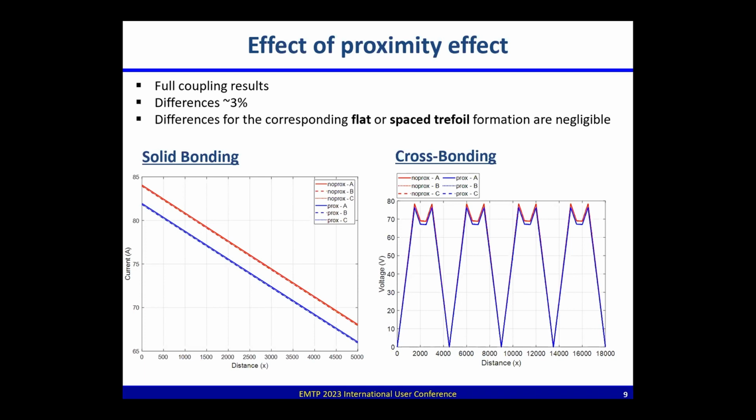Of course, because this is a trefoil case, the differences are observable. Let's say they're not that high, but they might be of interest from a technical perspective. But if we move to a flat arrangement or to a spaced trefoil formation, of course, you can understand the proximity effect would be negligible and can be neglected.